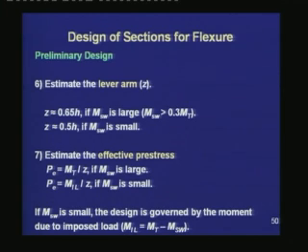Thus, we have some preliminary guidelines to calculate the total moment, then we calculate the lever arm, from which we calculate the effective prestressing force.